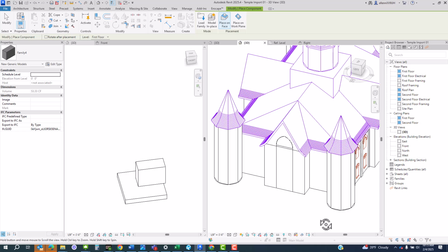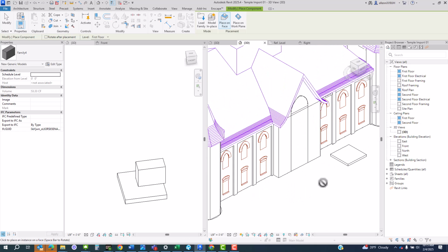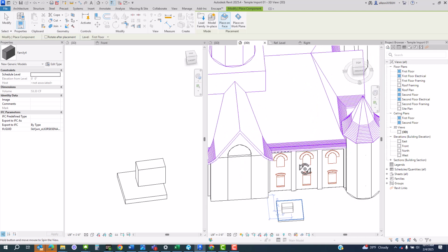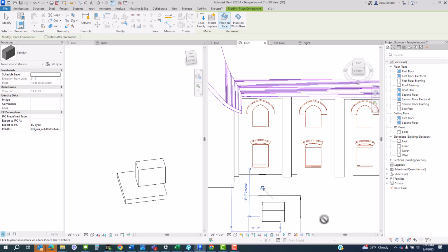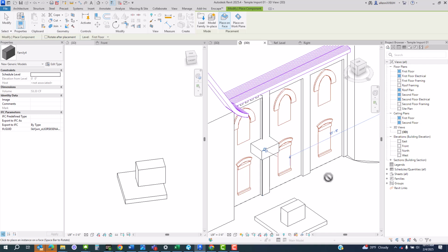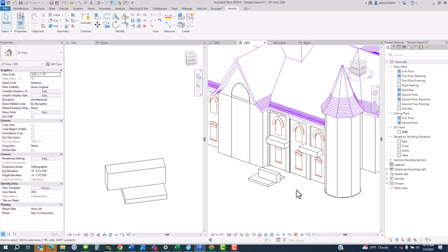You can notice here that it's not letting me place it on these towers, and that's because those are SketchUp towers. It's only letting me attach to anything that was modeled in Revit. And just like we thought, the insertion point is working, and there's the back of the object. Okay, that's Families 101. That's how they work, and this opens the door to all kinds of potential, so make sure you understand the environment, the tools, the work plane, and the host.